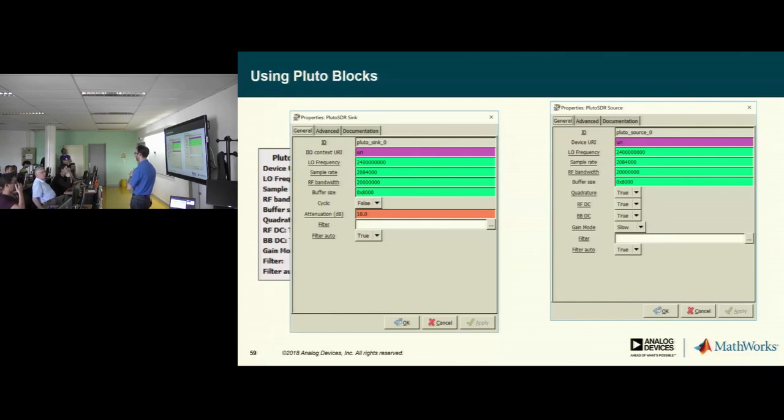So if you have a signal source block, like a sine wave generator, and connect that to the IO block for Pluto, it will take the first buffer that you're given, pass that to the FPGA, and constantly repeat. And then it will not accept any more samples. But this is super useful if you don't want to worry about contention on USB and guaranteeing that you're not starving the transmitter. Yeah, it's super useful for debugging.